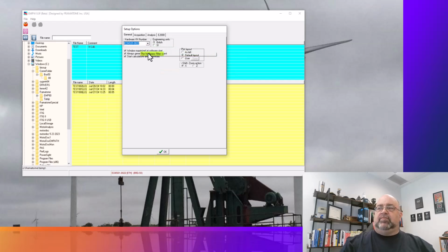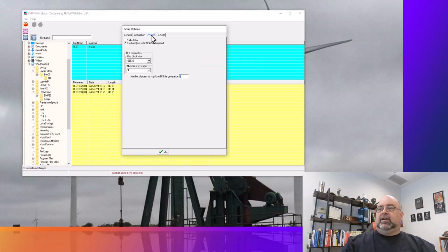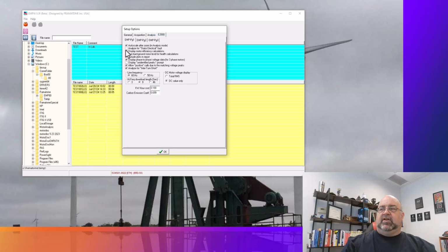Okay, so we have that. Whichever you wish here, check everything there. Next one is if I'm just installing the software, it usually shows this. Make sure it's at 65536. Leave the A to D card error message unchecked, uncheck calibration warning. All that's going to do is put up a button saying acknowledge me, and when it does that, it stalls the software. Make sure 65536, and here check all the boxes except for unidentified peaks. Again, it'll toss up a checkbox.